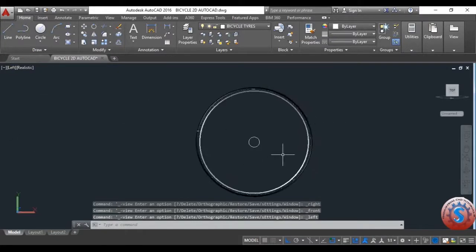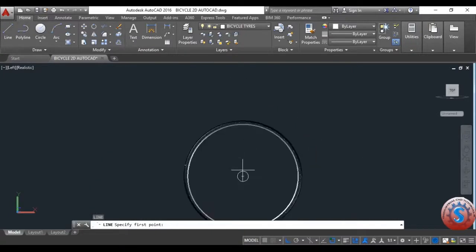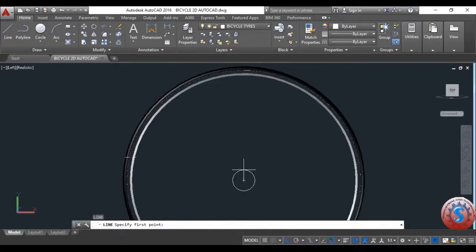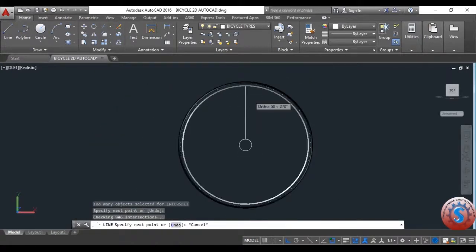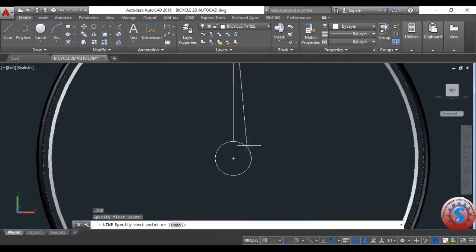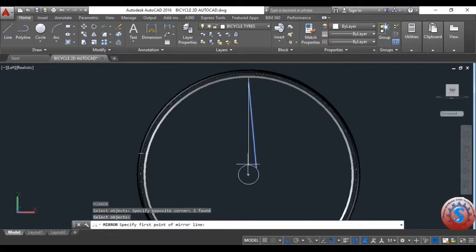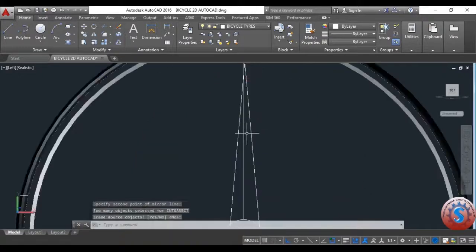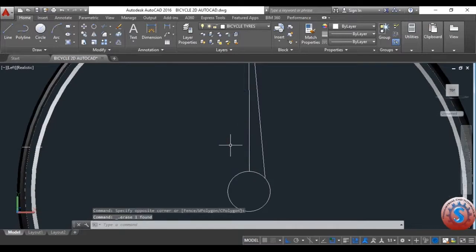Again the left view, and go into the line command, L enter, and select the line of any distance and make a reference line like this, and then give the line like this of some angle, and give the MI enter and select this. You can observe it is not the exact position. I'm deleting. MI enter.